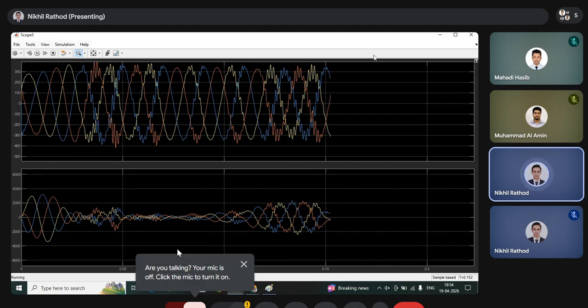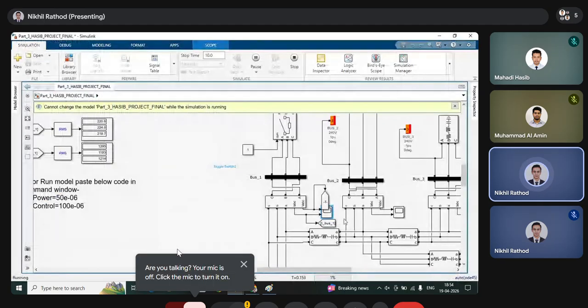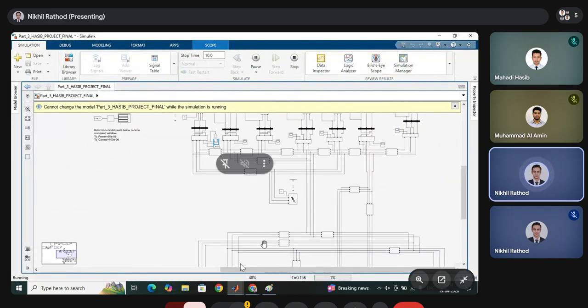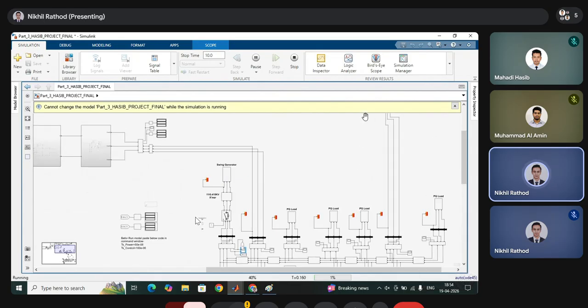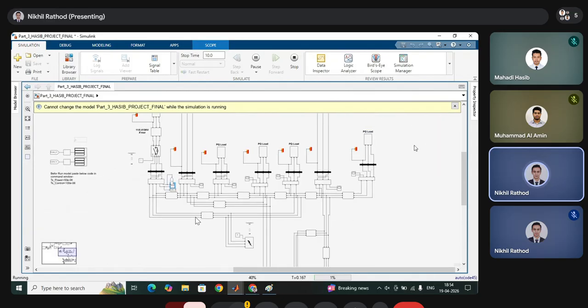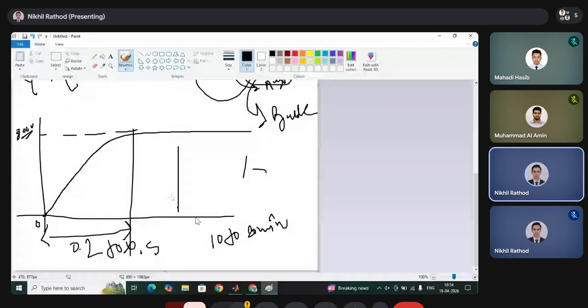So whenever any source is coming or being removed from the system, what the VSC converter is actually doing right now is taking a reference. So if you are isolating any part, or tripping any part, or causing any fault inside the system, the sine wave quality changes, as the VSC controller depends on the sine wave quality.